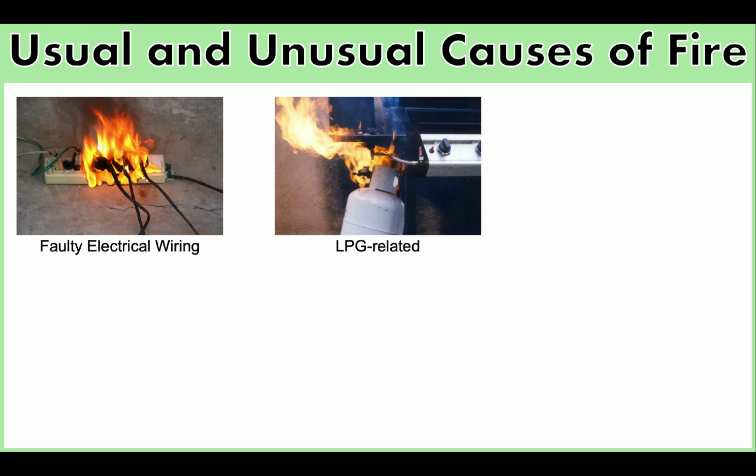Next, we have the LPG related fires. So, your liquid petroleum gas may leak as a gas or a liquid. Now, if the liquid leaks, it will quickly evaporate and form a relatively large cloud of gas, which will drop to the ground, as it is heavier than air. Now, LPG vapors can run for long distances along the ground and can collect in drains or basements. So, when the gas meets a source of ignition, it can burn or explode.